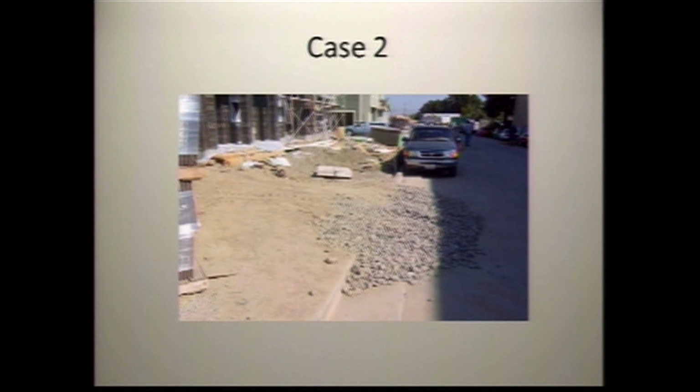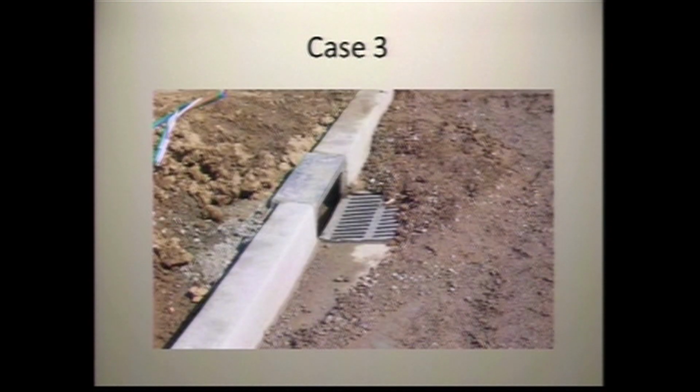And the housekeeping, this is big debris, but if a windstorm comes up, all that stuff is going to be blowing off the site. And where does it end up? It ends up usually in the creeks, because they're the low points of the landscape. It's where all the water flows. It's topographically low, so all of this trash tends to blow into the creeks, where the city again would be responsible for it. During the day, it's not windy. Is this a big problem? No, but when everybody's gone at night, it could get windy. The site needs to be cleaned up on a daily basis.